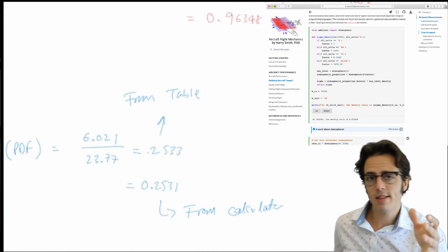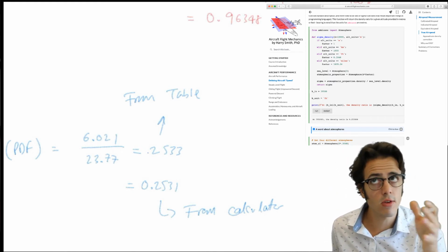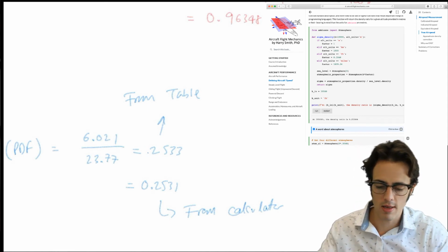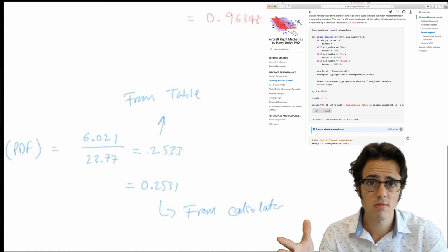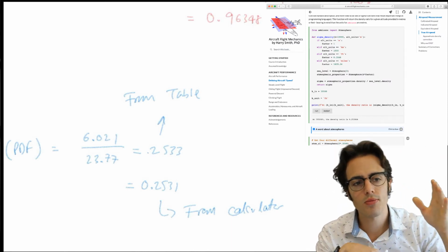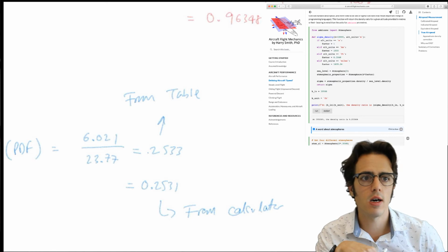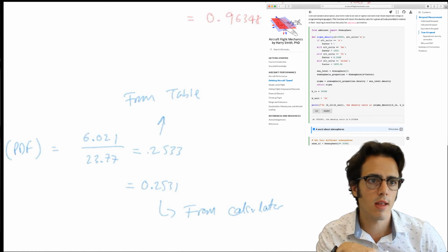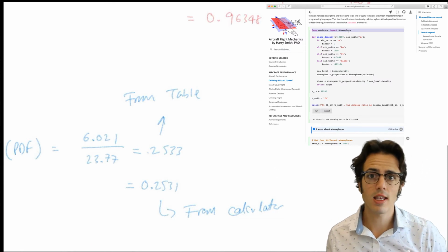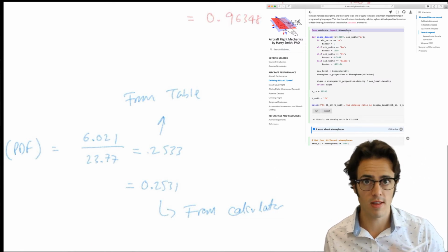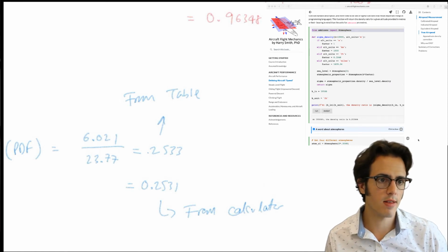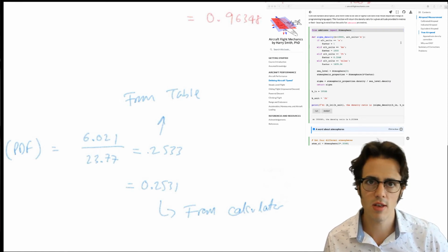There's the US Standard Atmosphere, and there's the International Civil Aviation Organization atmosphere as well. Both of these are ISA extended to go a little bit higher. They're exactly the same thing. What's used by ambiance to get the atmosphere is the ICAO atmosphere, the International Civil Aviation Organization. What's used to get the values in the table is the US Standard Atmosphere.